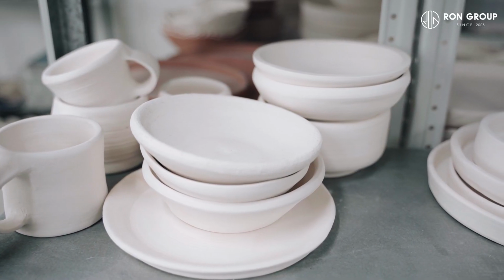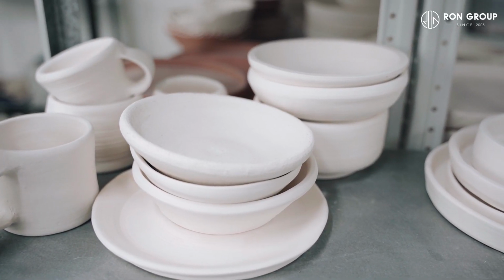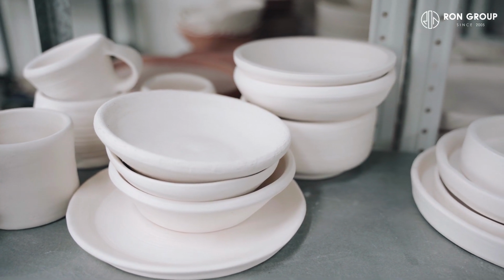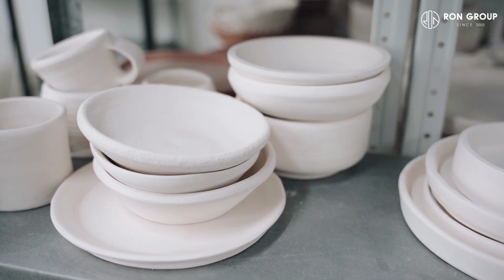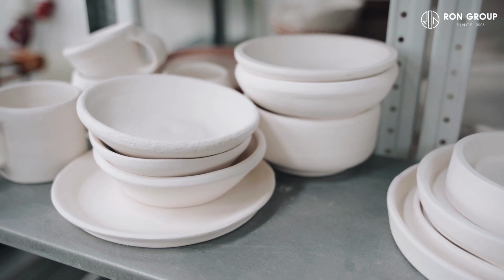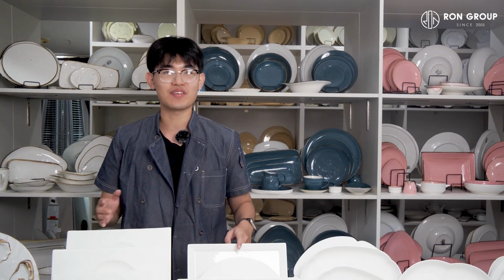Because the temperatures cannot reach those of high temperature porcelain, the glaze layer on the surface of the porcelain cannot fuse well with the porcelain body, and it is not very nice. The hardness is not as good as high fire porcelain, and the surface strength of the porcelain is relatively low and it is very easy to scratch. Over time, the glaze may crack on the porcelain and may leak.